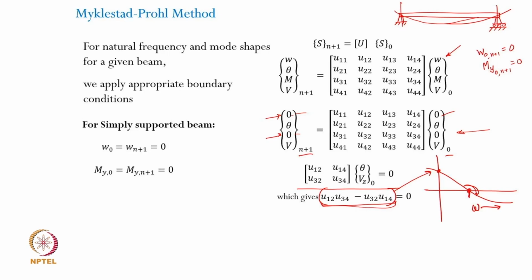Once that is done, that basically is your value of the natural frequency. You keep on doing this, later on at certain other higher value of omega, you will find the next sign change that becomes your second natural frequency, and so on, okay. That is how you do it, and that is what we learned in the previous Holzer method, the root searching method.